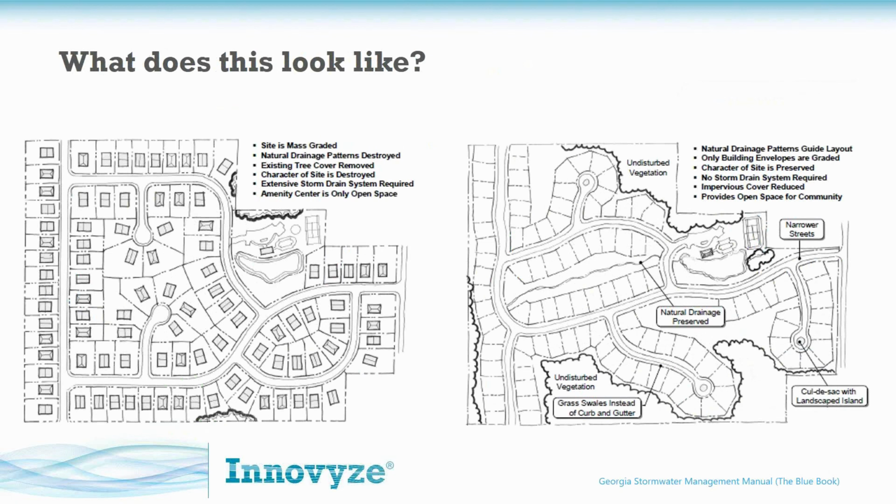So you see here, on the left is maybe kind of a classic subdivision. Everyone's lots are exactly as big as they can be, and there's one big pond. The issue here is this doesn't feel like a good communal space. There's not perhaps a lot of walking, not a lot of, I guess, community engagement points, and probably some stormwater issues, some backyard flooding, okay? Well, on the right, we can have as many lots and preserve, don't infill creeks, right? Keep these natural corridors, natural vegetation, and we're going to have a lot more aesthetically pleasing, a lot more of that community feel to these developments.